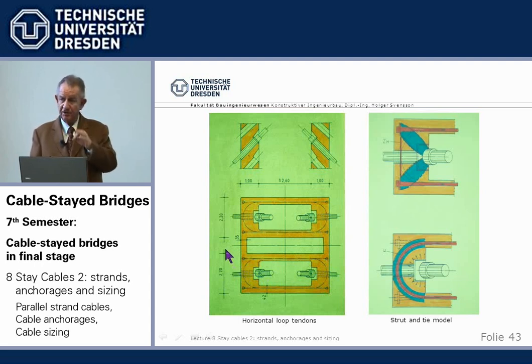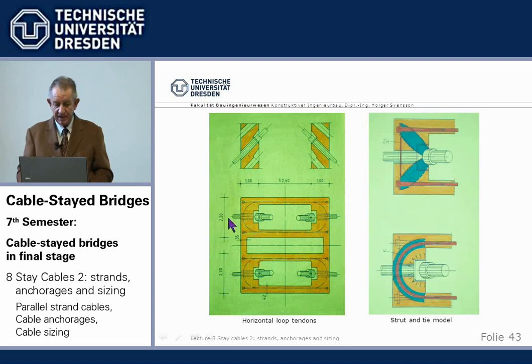And this is for the material concrete. The appropriate solution is to post-tension it. And if we think about it, we use what we call a strut and tie model, Fachwerkmodell. Strut, compression member; tie, tension member. And say, okay, I use overlapping loops like this and like this.